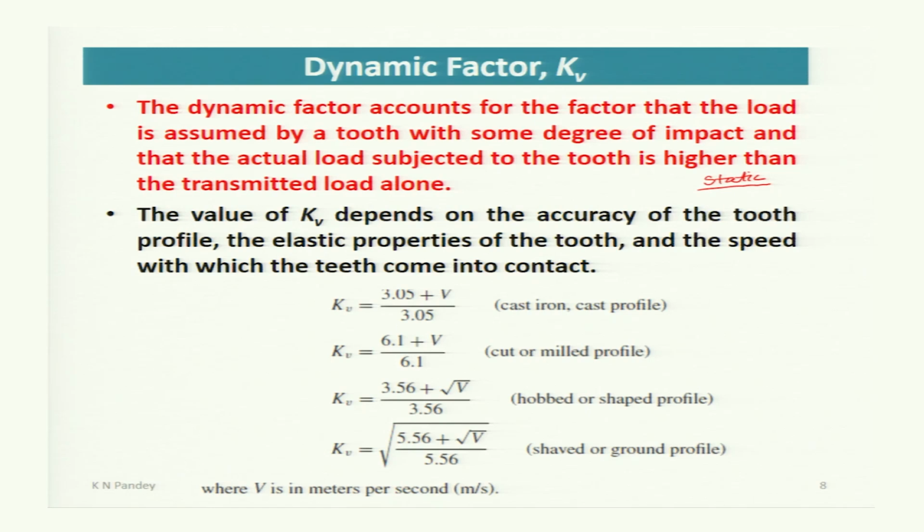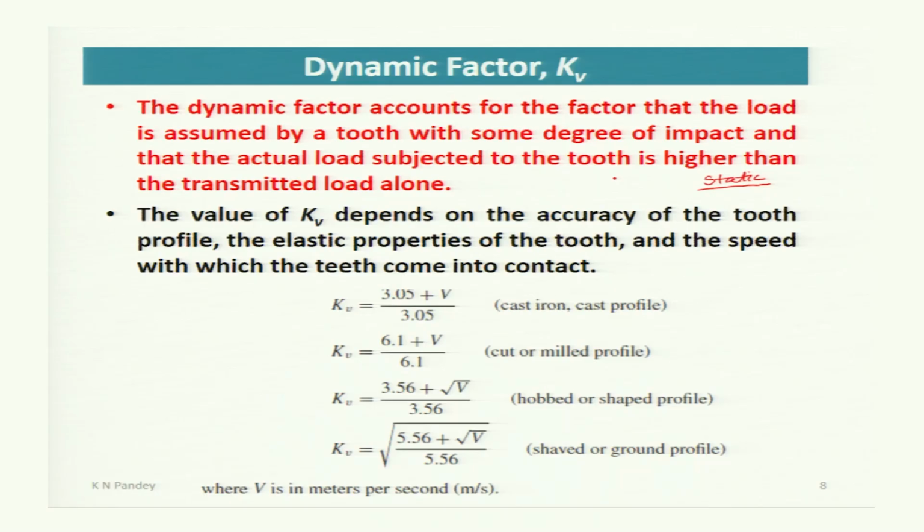And we have studied that when there is contact, then load acts on the gear tooth, and after disengagement till the further engagement, there will not be contact, and so the force is dynamic and the gear is moving, and so there will be the effect of dynamic factors. So that is accommodated by multiplying the basic equation of bending by the dynamic factor Kv. The value of Kv, the velocity factor or dynamic factor,